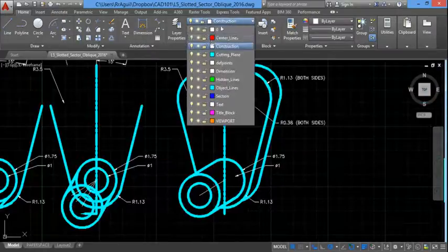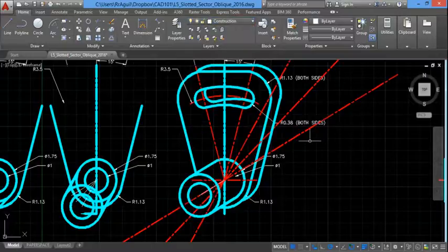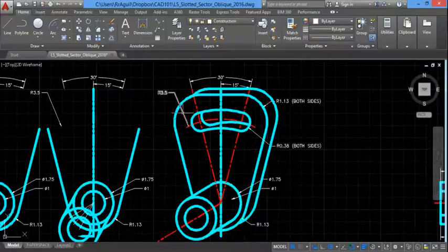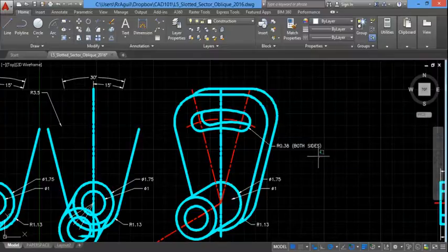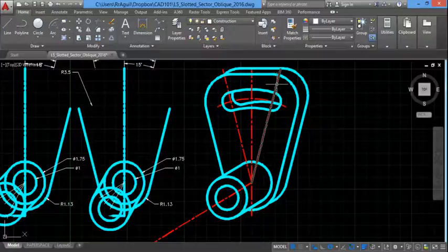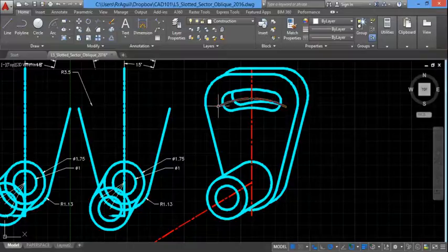I'm going to turn the center line back on, remove all of my different angles that I had. No dimensions are required on a pictorial drawing, so please remove those as well. Then this object, this cutting plane line will become a center line. None of this information is relevant. Nor is this.